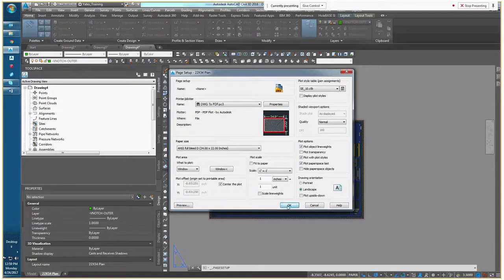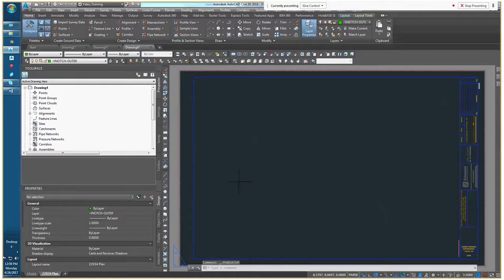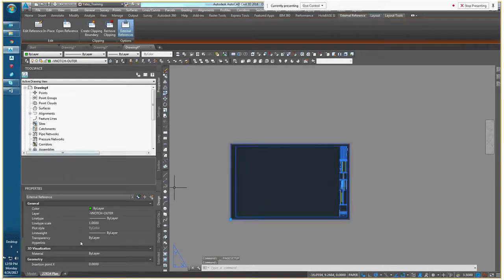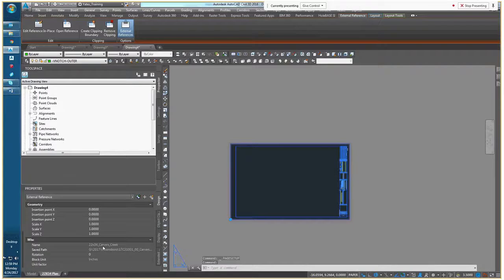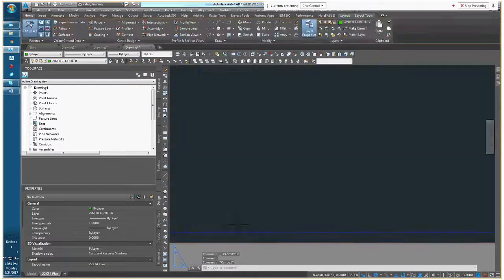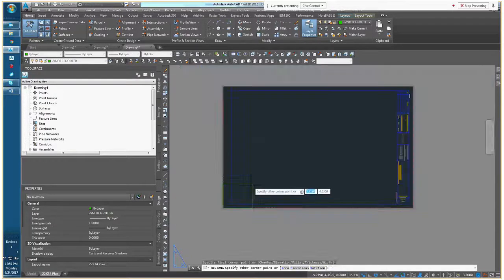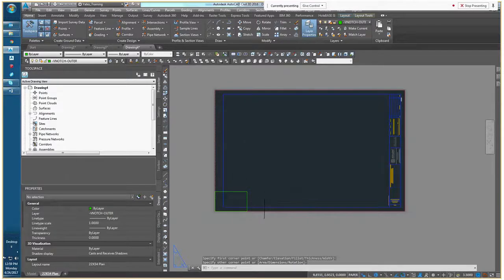Say you know that you've got a 22 by 34, but this object comes in very, very small, down here in the bottom right-hand corner, only comprising your entire title block. Looks like it's just taking up a little bit of space down here in the right-hand corner, about like this size. That's pretty common for some blocks when you insert them to be out of scale by 12.